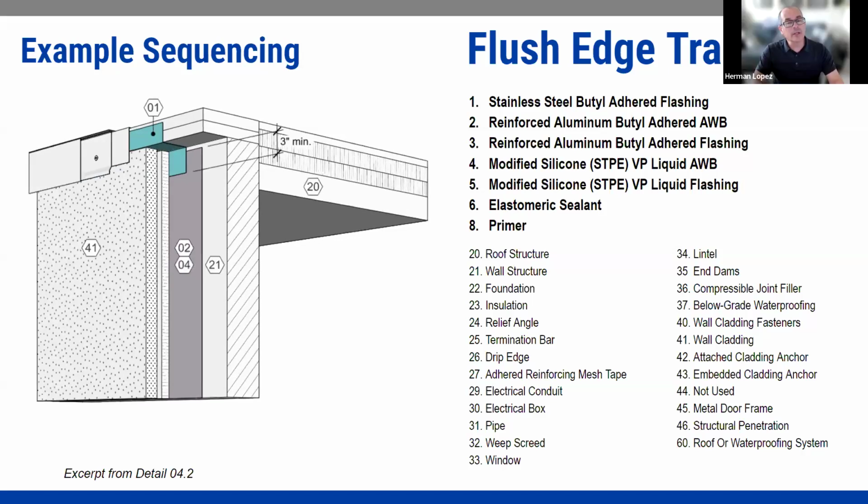Ben, I always like to point out on this detail that integrating the building envelope to the parapet material takes a little bit of planning and strategy, because at times you're going to seal up that parapet before you put on that weather barrier, and installing the weather barrier after the fact, you may end up with a reverse shingle. Right. It just takes some planning, and it takes an installer who understands and trades talking to each other, which may be a presentation for a different time, right?